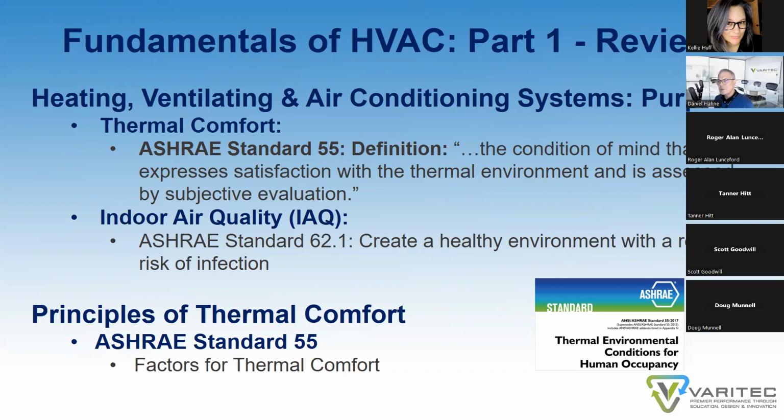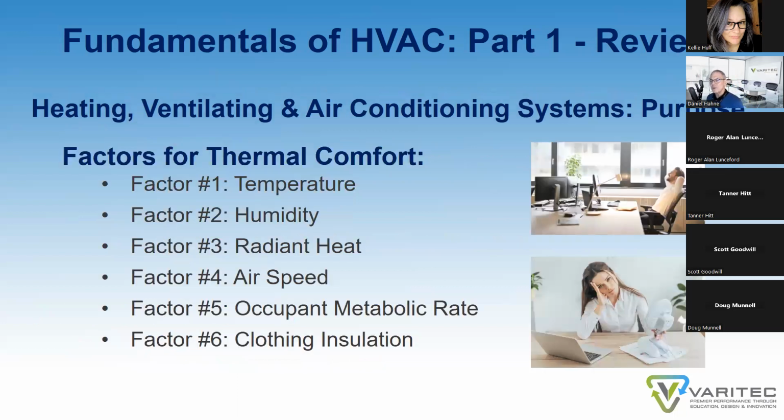Also, HVAC is to create better indoor air quality by maintaining proper ventilation rates, bringing in assigned minimum amounts of outside air to allow us to maintain a healthier environment. We also explored ASHRAE Standard 55 and the various factors that contribute to thermal comfort. We looked at temperature, humidity, radiant heat, airspeed, occupant metabolic rate, and clothing insulation. Six factors that affect an occupant's sense of being comfortable. And we explored those in detail.